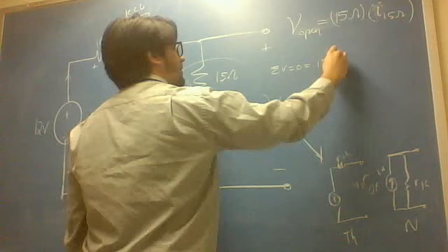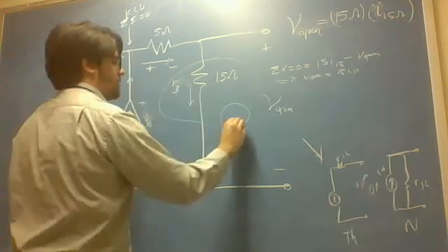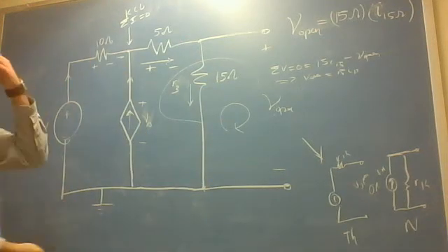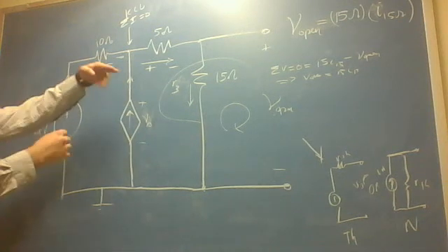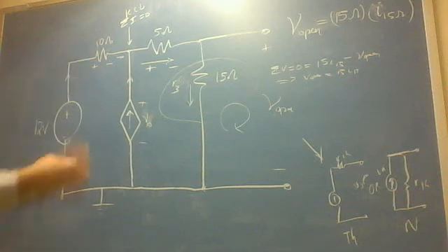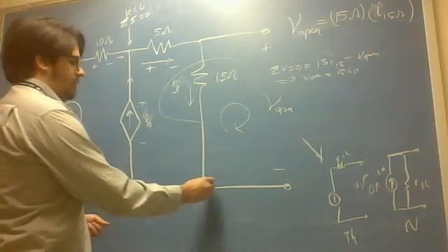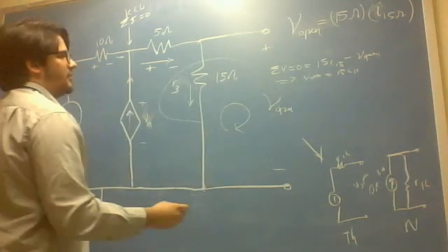So that's the reason why, if you do a mesh around here, you get that, right? Well, if it's not already obvious, at this point it should be, hopefully. When you see something like this, where you could theoretically think of a voltage between here and here, just think of it as if you're measuring the voltage between here and here with the probes. So the voltage would read whatever the open is, right? That's usually how I think of it.